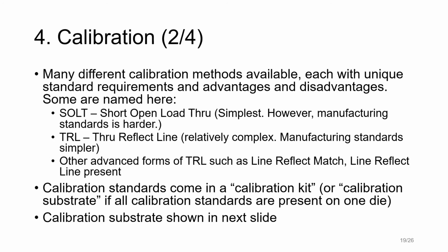SOLT algorithm, for example, requires precise standards in probing. However, TRL and its advanced versions are relatively tolerant to the same. This makes manufacturing the calibration substrate for SOLT harder.